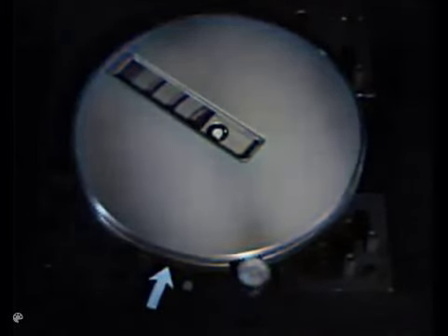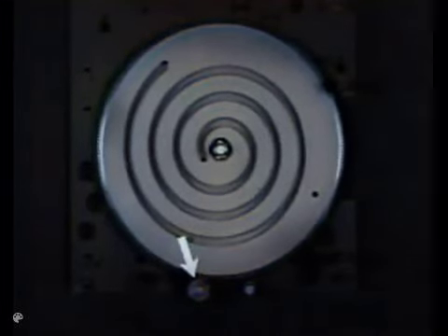Under the slotted vector gear is a cam. The cam surface is a spiral groove cut in the face of a gear. The cam is positioned by this input gear. A follower, with a projecting pin, rides in the groove.